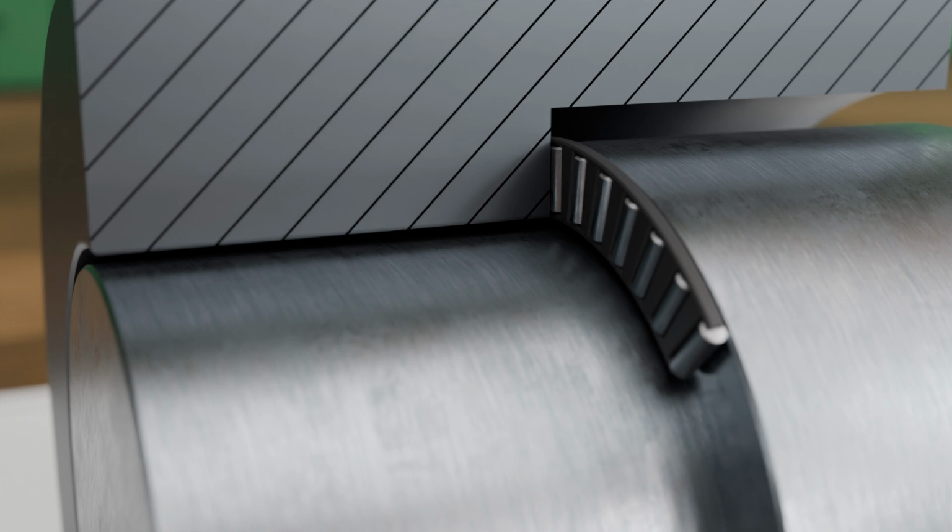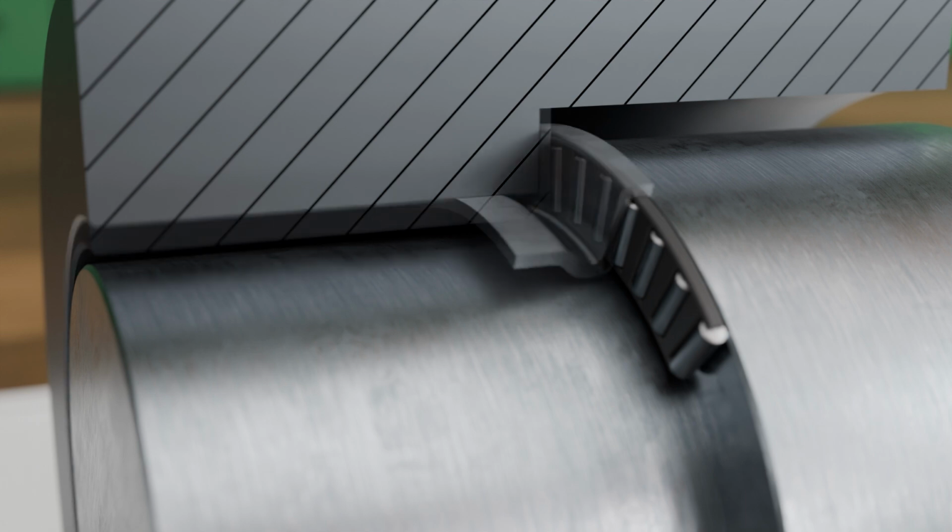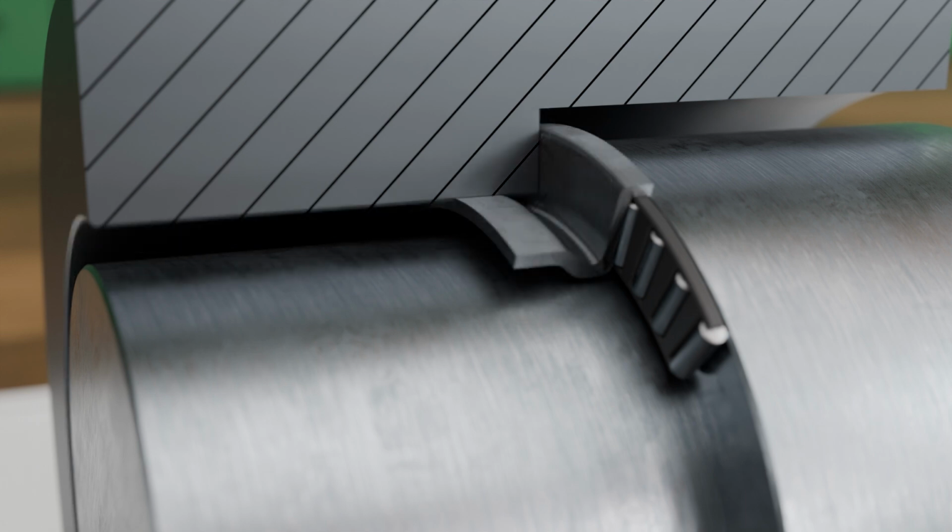This bearing design is characterized by an especially low overall height and is often used in combination with radial bearings. Thrust needle roller bearings are also available with a so-called centering flange. This centering flange ensures precise alignment of the washer in the housing or on the shaft, thereby simplifying assembly. At the same time, it prevents the washer from shifting during operation. When the rolling elements are in direct contact with the shaft shoulder, this surface must be ground and hardened. This bearing design offers a compact, easy to assemble, and cost-effective solution.